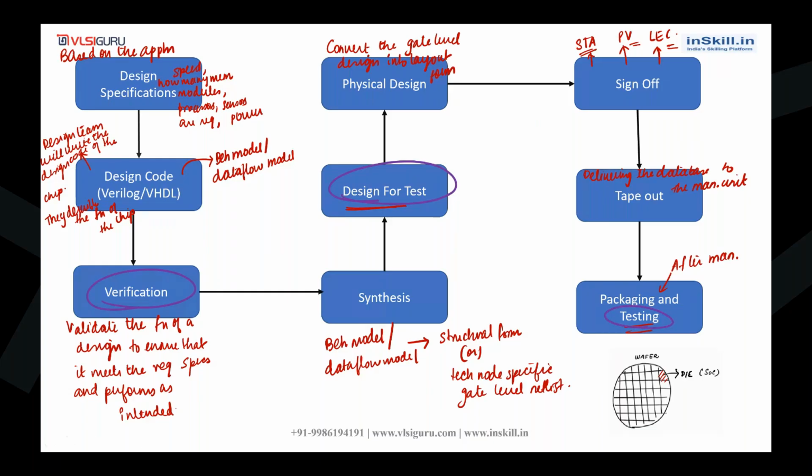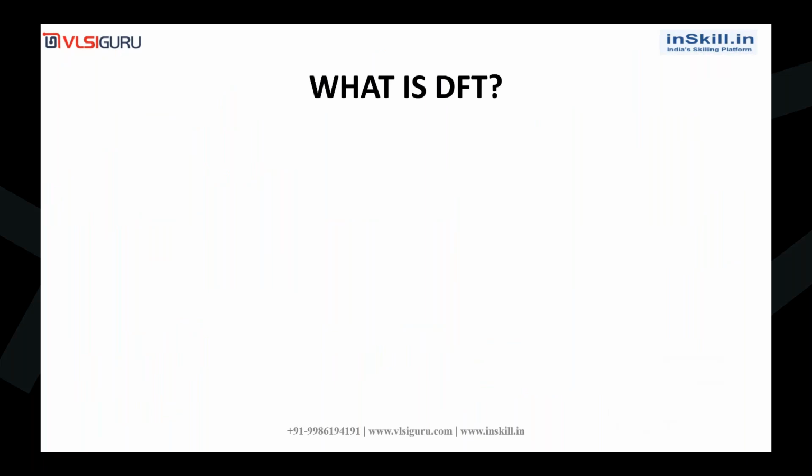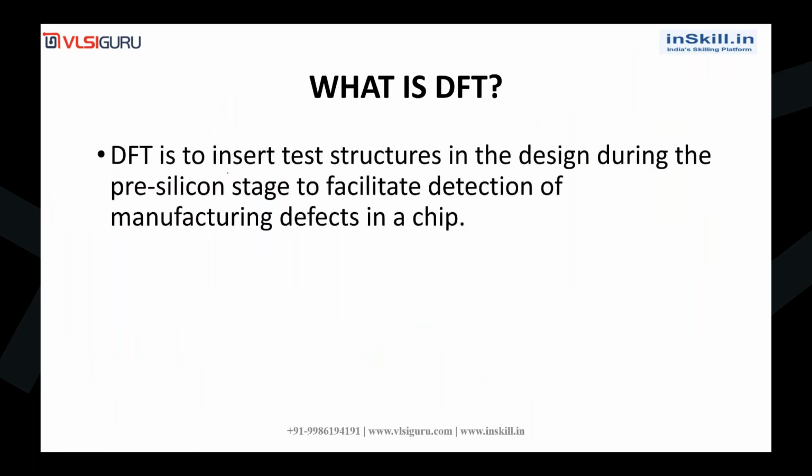Okay. So what is DFT? DFT is to insert test structures into the design. We will be adding our own test structures into the design, like scan insertion, MBIST insertion, boundary scan insertion. During the pre-silicon stage, which means before manufacturing, to facilitate, which means to help, detection of manufacturing defects in the chip.